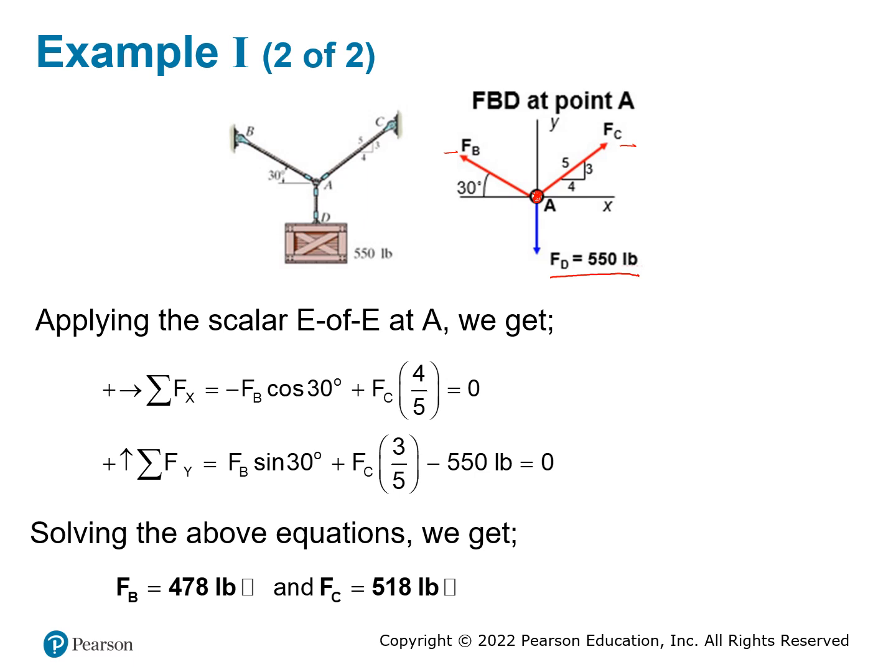For the sum of forces in x, with this direction positive, what are the forces that are acting on the x, y axis? This one is not going to make any difference in the x direction because it is purely in the y direction. We have a component from this one here. You can decompose this force into the x direction here. This will be the FC at x. You can decompose this one here. This will be F of B of x. So you sum these two together, and then you can get this equation right here.